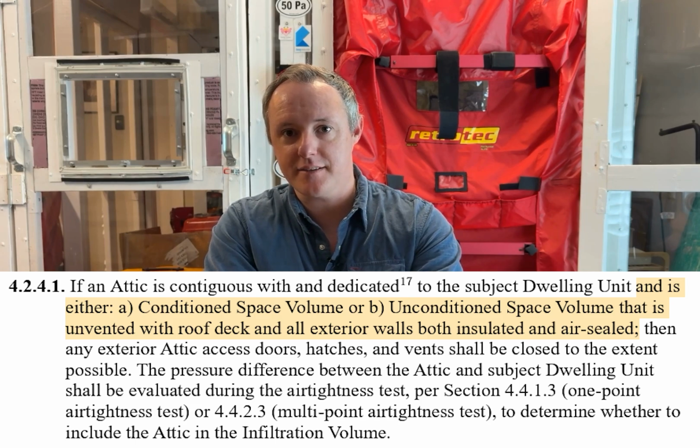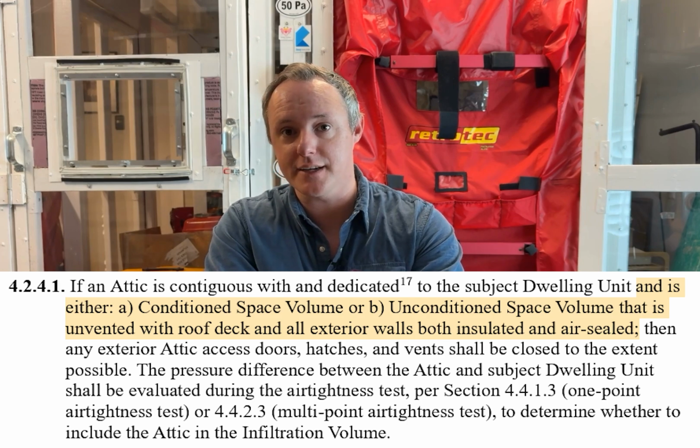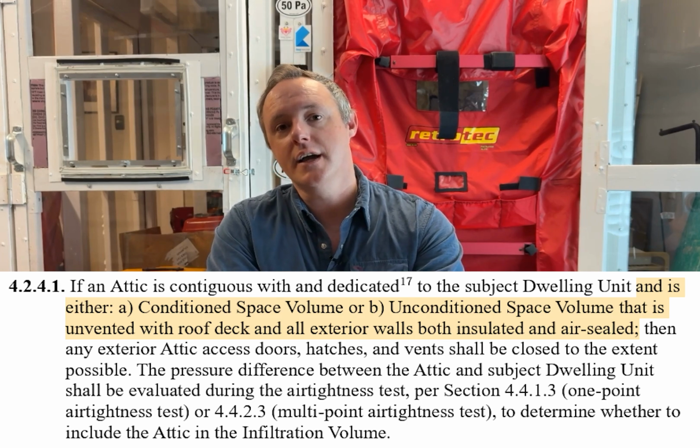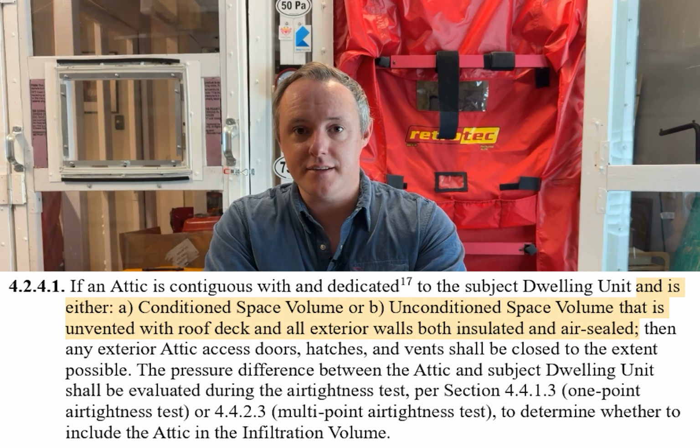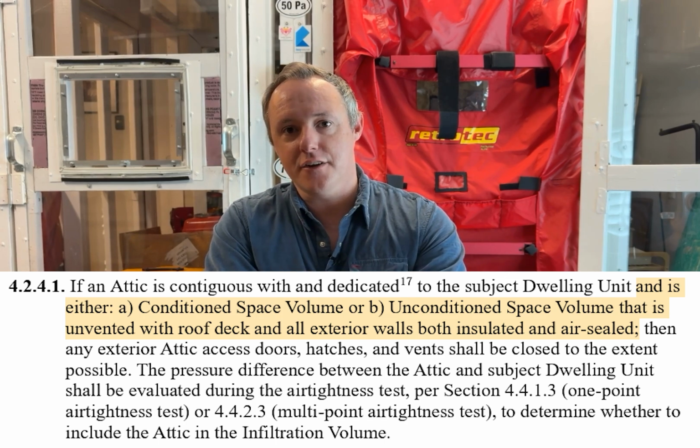So the next part of the criteria is that one of two things has to be true. Either that attic space has to be part of that condition volume, which means it's deliberately served by the HVAC system, or it has to be unvented but have the roof deck and gable end walls air sealed and insulated. So if the attic is dedicated specifically to that unit and it's either deliberately conditioned or unvented, air sealed and insulated, then you can include that as part of your infiltration volume.